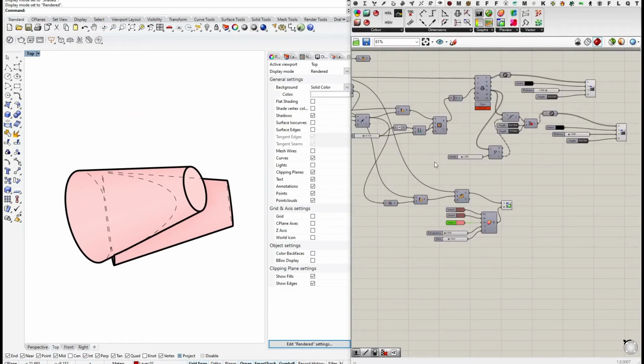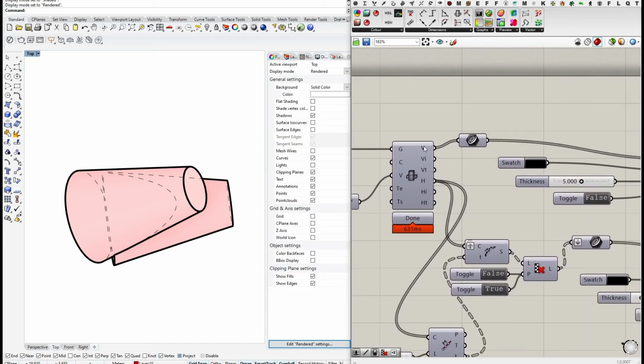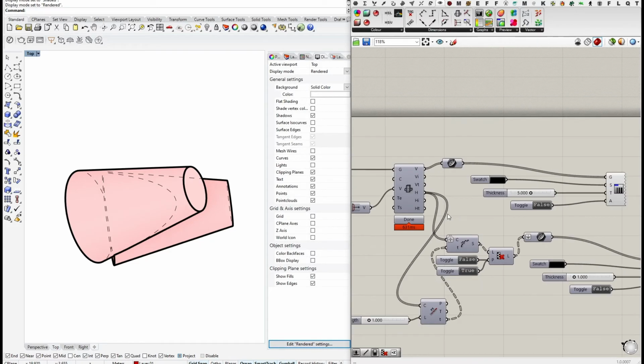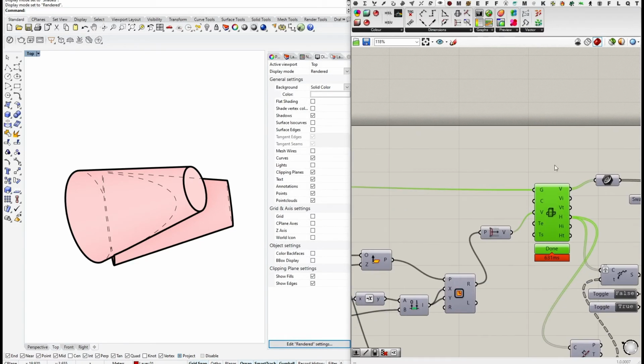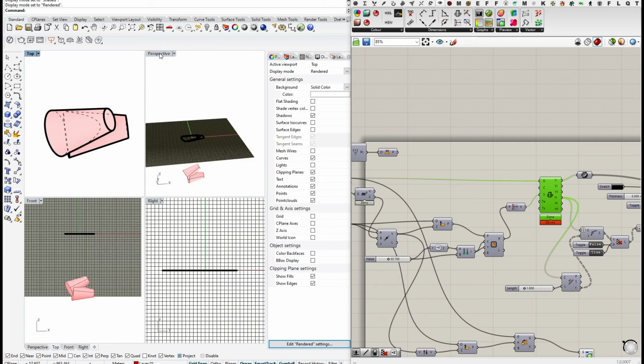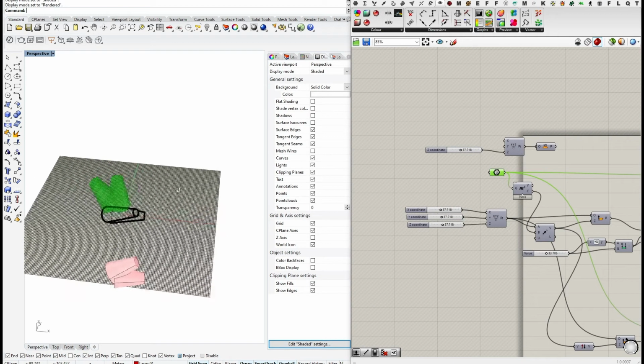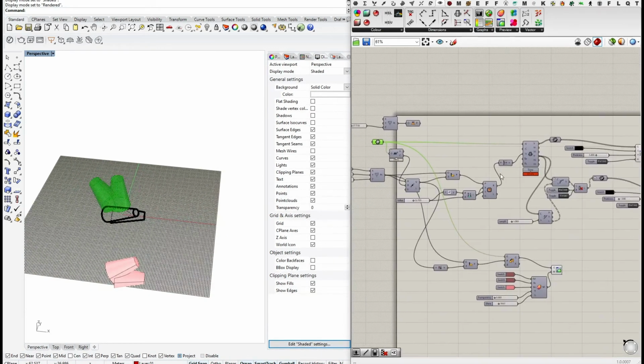But now let's say you want to have a very specific curve of your object, like this curve or another one, highlighted in a hatch mode. As it is really not practical to work with the outputs from the Make2D drawing, we will need to extract the curve from the 3D model first, from our Grasshopper 3D model here, and do a second Make2D operation in order to use that.